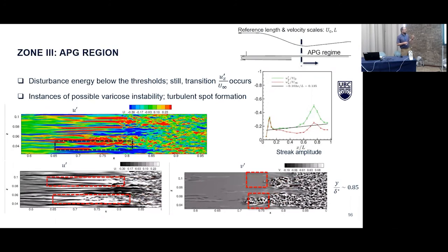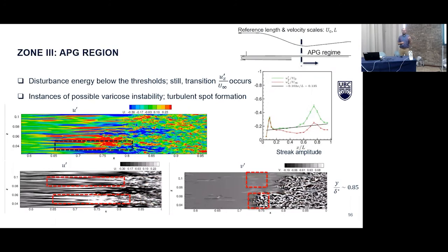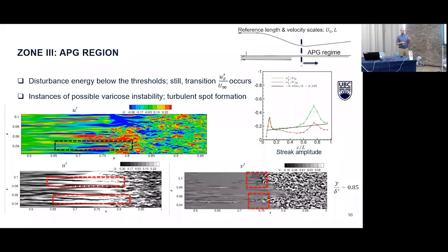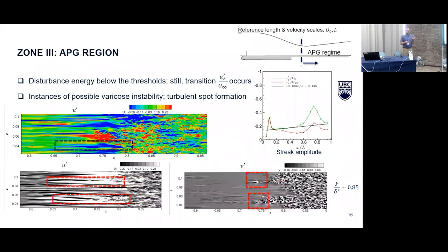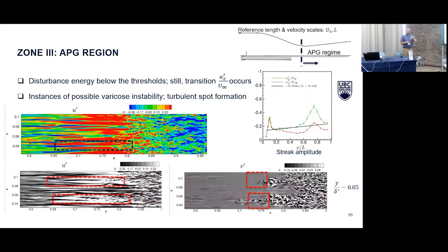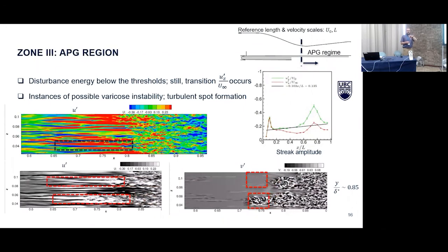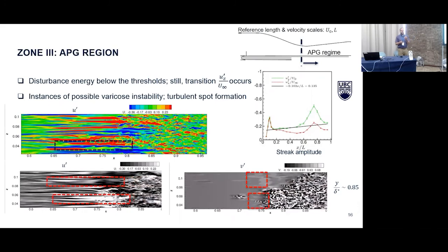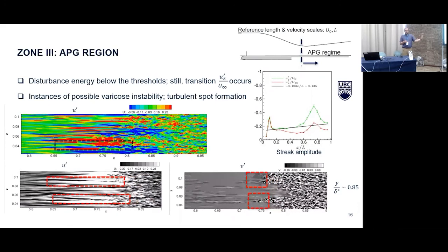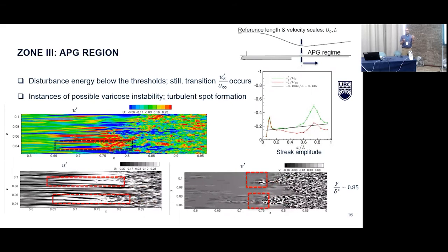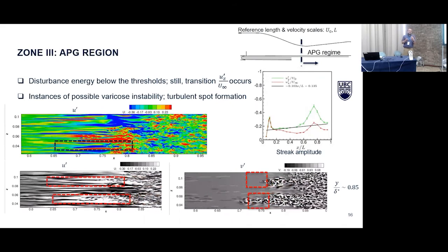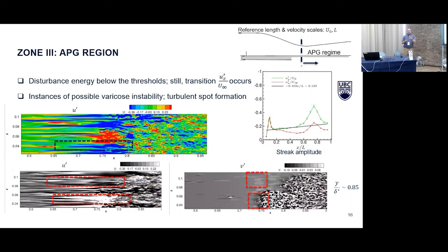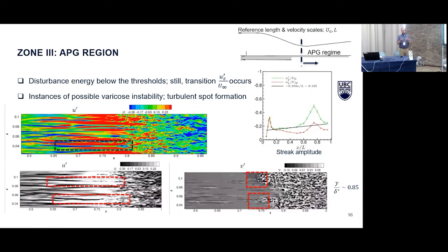And the generation of these turbulent spots really mimics bypass transition, insofar as we have these streaks that form very rapidly small scale turbulent structures that are hairpin shaped, that resemble the types of turbulent structures that you see in a fully developed turbulent boundary layer. They straddle the streaks, and we can see that there's a coincidence with the motions of the streak and the creation of these turbulent spots.